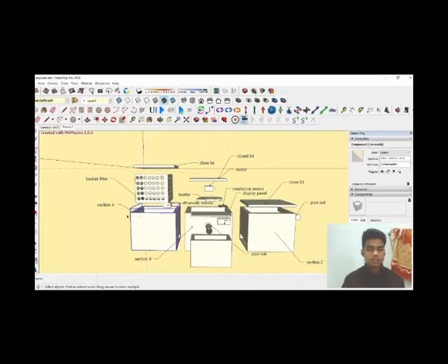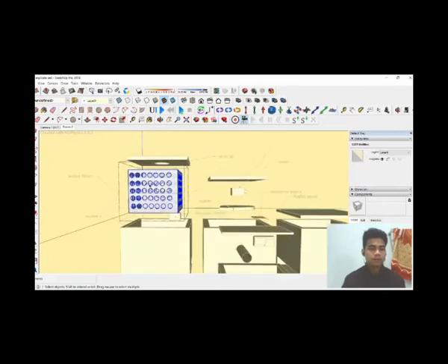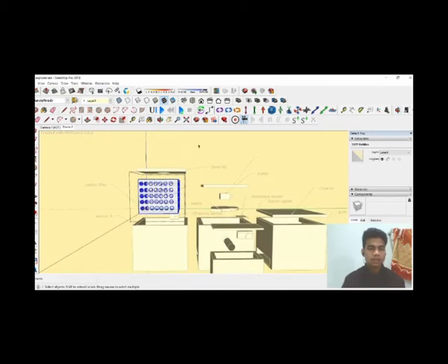and section A is for the solid, section B is for the oil filter, for filtering the oil, and section C is actually for the water, the wastewater already cleaned out from the oil. So this is a bottle for the oil, so the oil can be stored here. You can see the basket, I zoom in. This basket filter is for filtering the solid waste when the water goes through this part, it can filter the solid part.